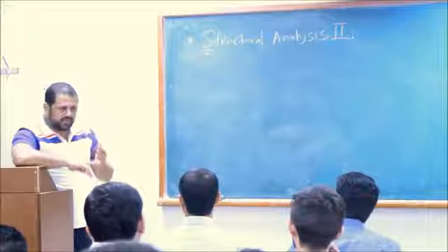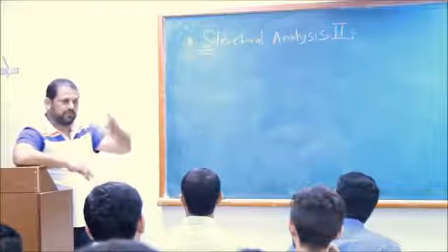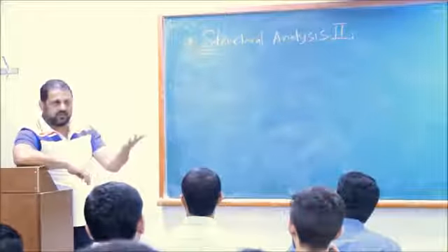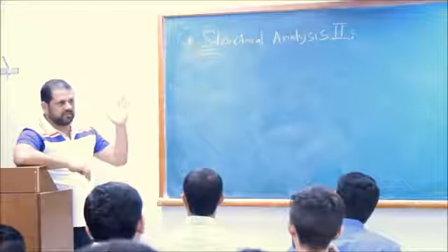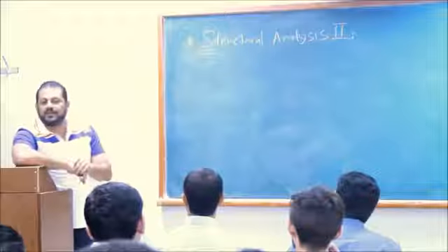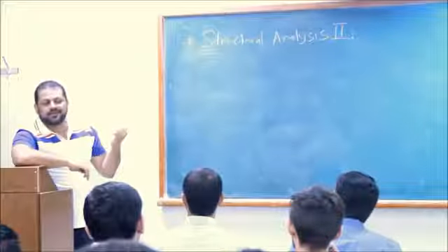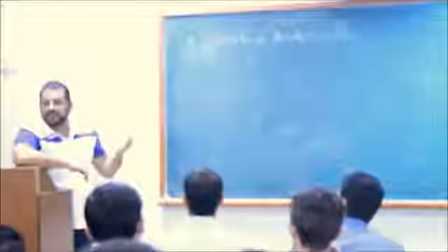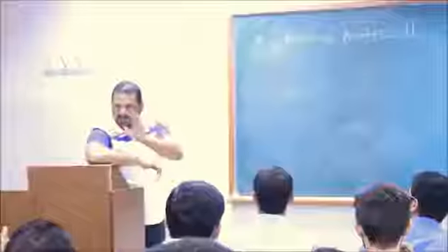You covered at the beginning determinacy, right? We know how to check the determinacy. We calculate the unknowns. How many equilibrium equations we have, we check. If the equilibrium equations is the same as the unknowns, good, determinate. If the available equations are more than the unknowns, unstable. If the available equilibrium equations are less than the unknowns, indeterminate.